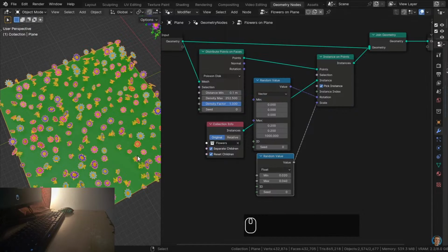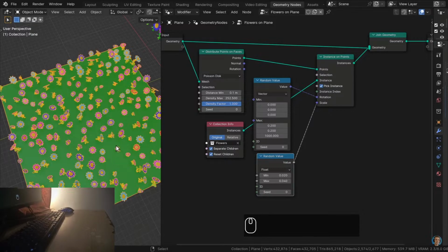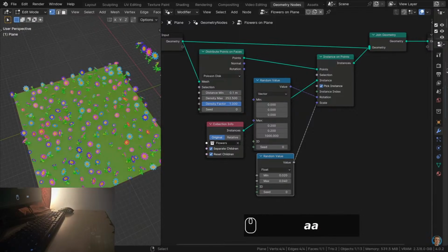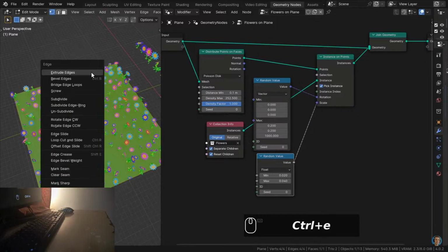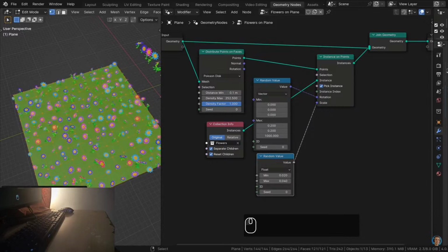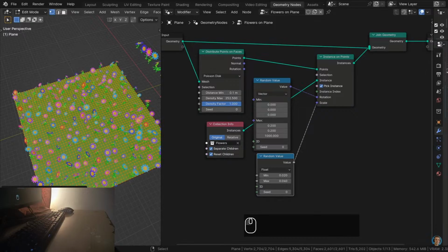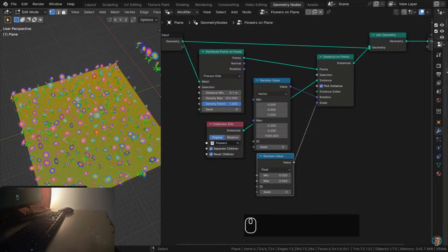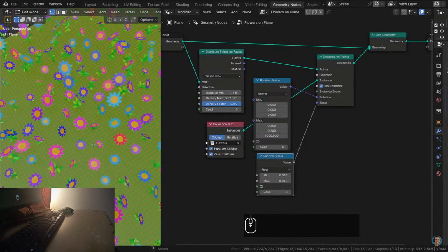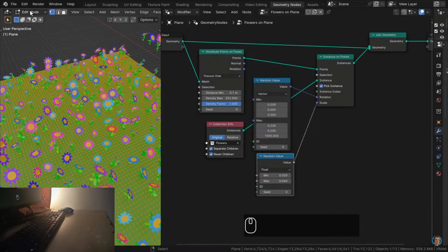Now in order to weight paint, we need to subdivide the mesh, because the weight painting uses the vertices of the object. So let's hit the tab key to go into edit mode, and I'll select everything, and then you can press Control E. Control E will bring up these settings, and let's click on subdivide. And then after we subdivide this, let me just move myself out of the way. Right next to me on the subdivide here, we can turn up the number of cuts. So I'm going to turn this up pretty high to like 50, maybe even more. So let's turn this up to like 80, so it is very detailed. And now I can close this. Why I'm making this detailed again is because the weight painting will be more detailed if there is more geometry. So now let's go here to edit mode, and we can change this to the weight paint.